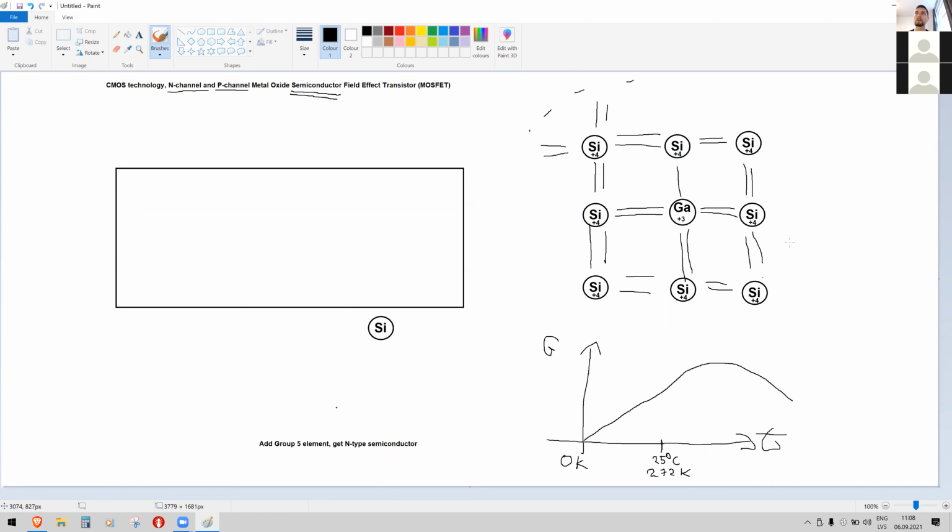But what happens is, it turns out, well, you would think that this material doesn't conduct electricity because there are no free electrons. But if you heat this material up to room temperature or something like that, and you put some voltage across it, basically some electron gets heat energy high enough that it just jumps from one bond to the neighboring bond.